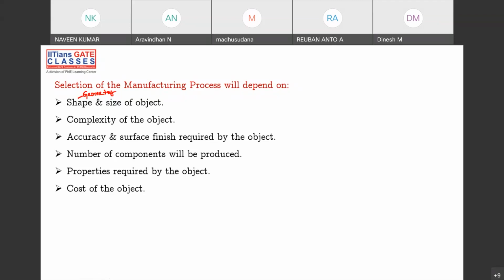Yes, very good, excellent, Praveen. Yes, grinding. Obviously, if you want to increase the accuracy, grinding should be there. In grinding itself, there are so many different wheels that we have: coarser grain grinding wheels and finer grain grinding wheels. Based on that, your surface finish will increase or decrease.